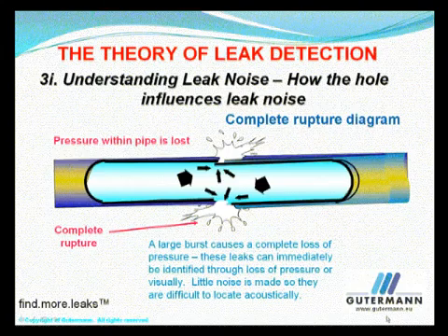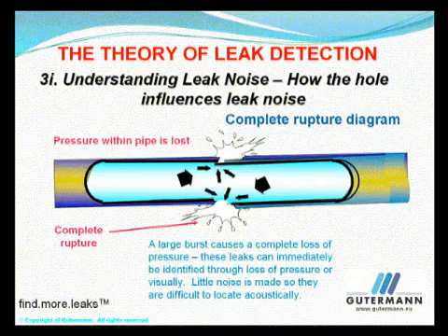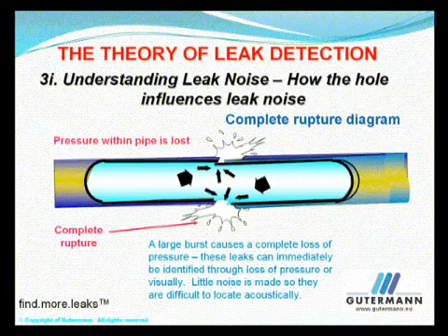Ruptured leaks. When you've got a complete rupture, there is little noise, as there is a complete loss in pressure with no resistance to the water escaping. Trying to find these leaks with acoustic equipment is very difficult. However, they're quite visible, often jetting up into the sky.